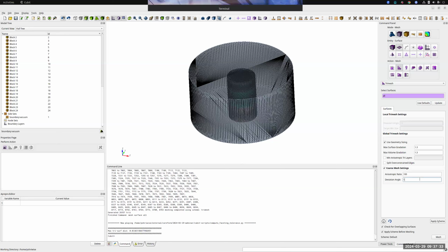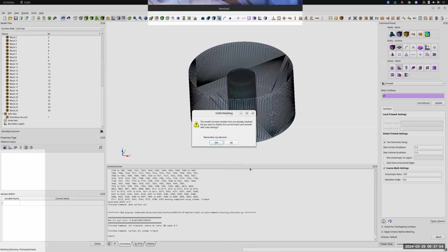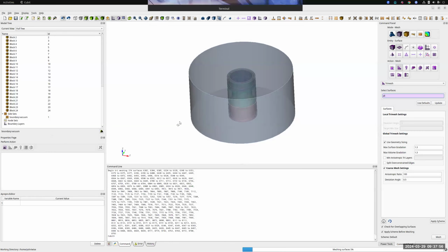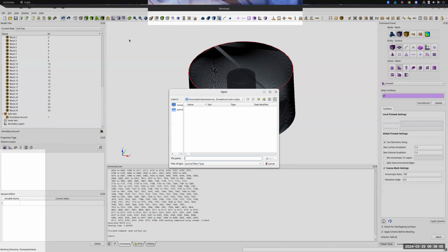And so I used a deviation angle of 1, and we got something like, down here we see in the console, a distance of 0.03 geometry units, and in neutronics units, that's going to be 0.03 centimeters. But if I used something instead, like potentially a deviation angle of 0.5, and I remesh this model, overriding all my previous mesh, I can visually see that the triangles are now more dense on this outer volume.